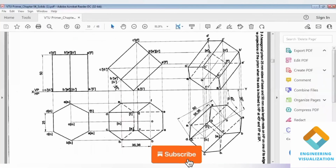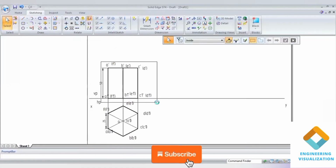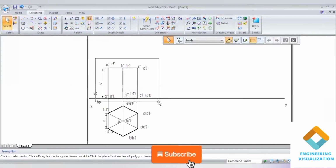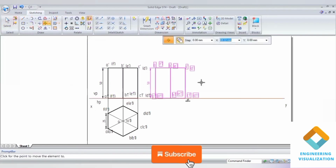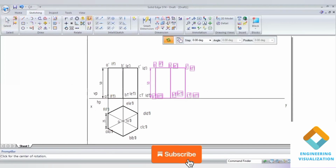Okay, and we need to incline with the base edge. So inclination to the base edge is given. Actually they'll give the angle of inclination to the axis, but we need to incline with the base edge inclination. Okay, it will be easy in order to do the inclination. So use the move command, create a copy, slide along the XY line, and go to rotate and take the base edge.